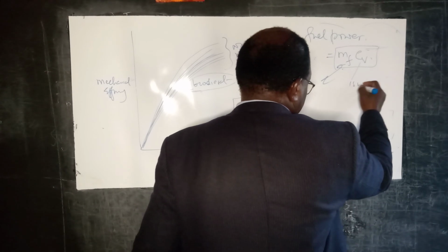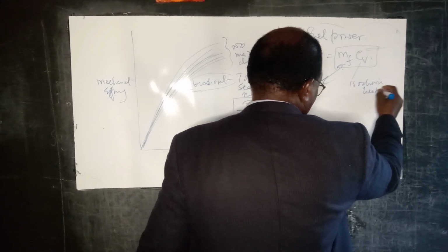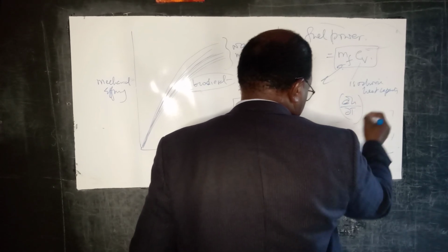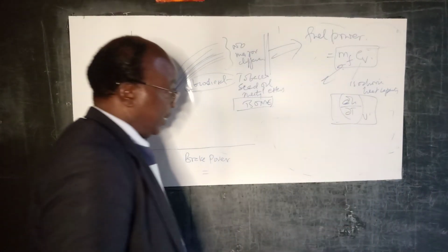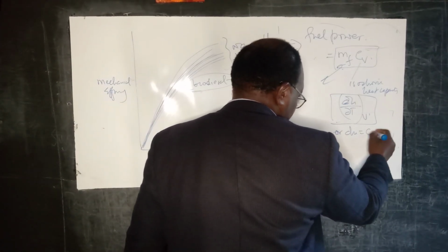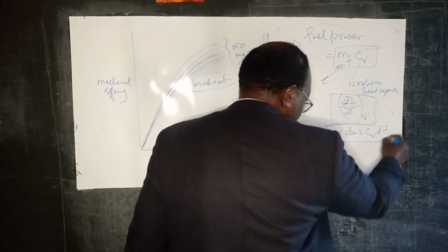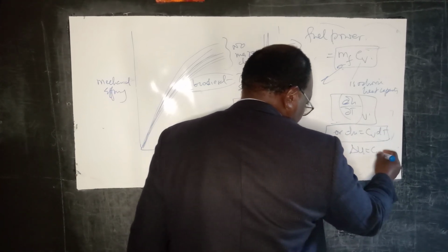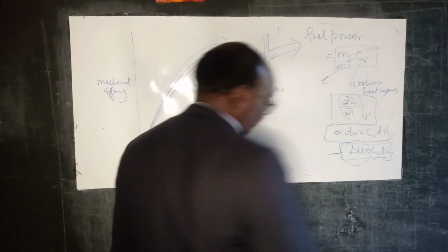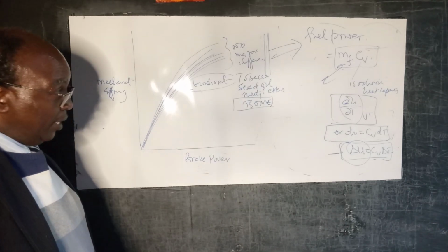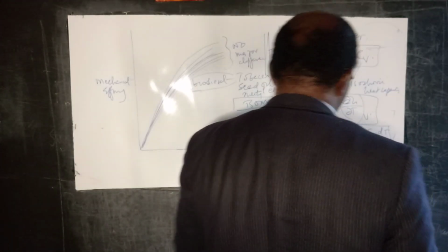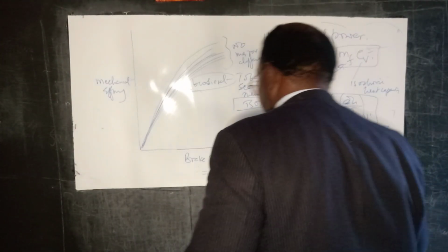That's just the caloric heat capacity, which is simply the change in internal energy with temperature at constant volume. Or you can think of dU as being Cv dT in infinitesimal terms, or delta U is equal to Cv delta T. So that particular quantity gives you basically the energy content of your fuel, and it's a very important unit. So the fuel power, just multiply mass flow rate with what you have in terms of the heat capacities.